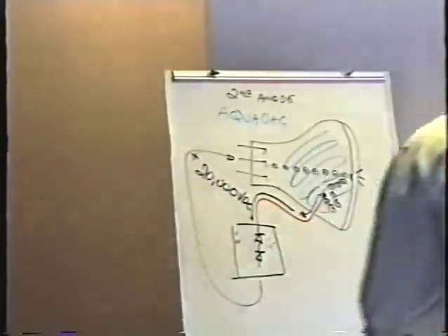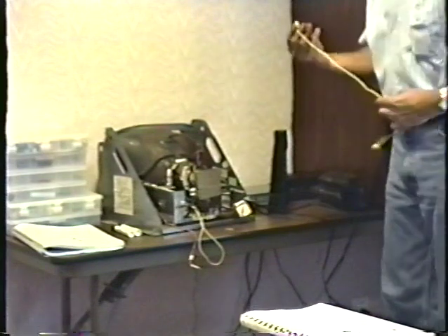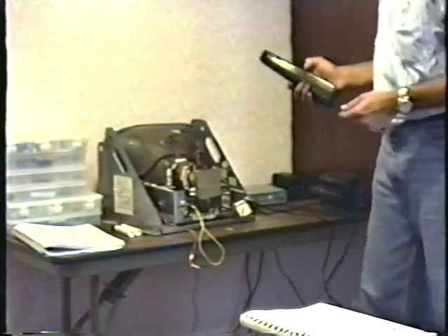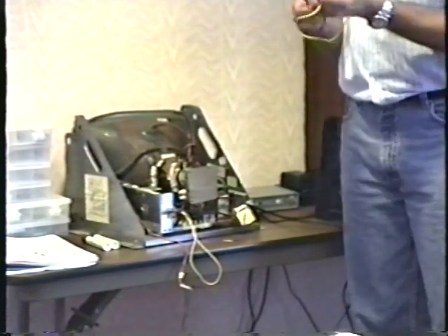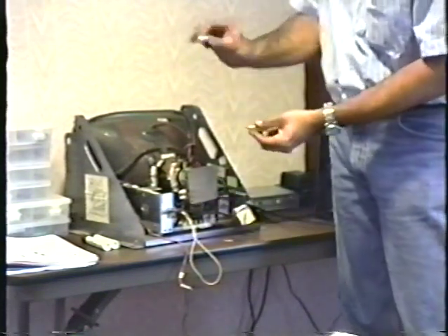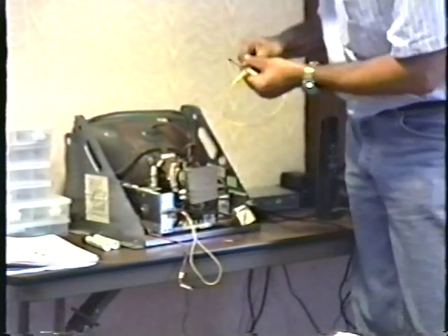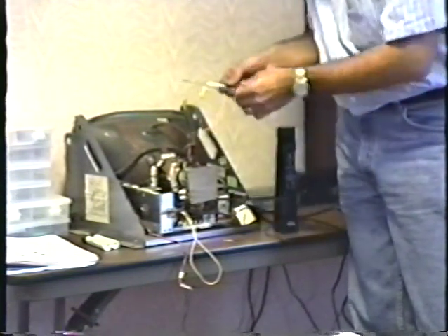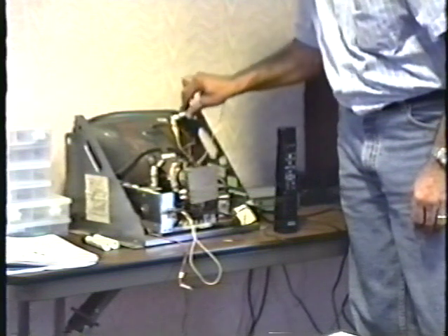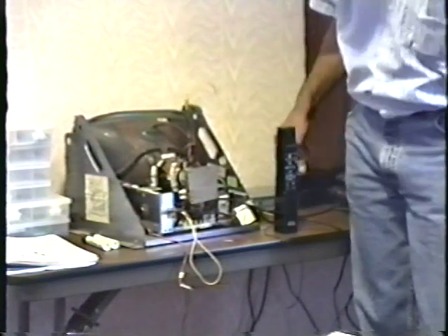Now, I can show you that the picture tube is fully charged here. If you take a clip lead and a screwdriver with an insulated handle, and this one is insulated, ground the other end of the clip lead, connect it to the chassis, and if we listen, we might be able to hear the snap. Definitely. And yet, when I was touching the thing, I wasn't getting a shock at all.